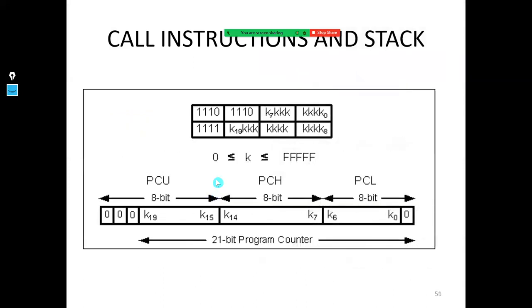So this is the opcode of the call instruction. Okay, so I have 1110, and then we have 11. Let's correct this. Then we have 110 S. S is for the shadow register. Let's make it, for the moment, the default value, which is 0. Here, let's suppose that we have 1100. And then we have the rest of the bits.